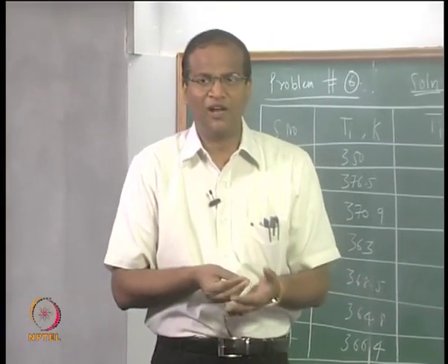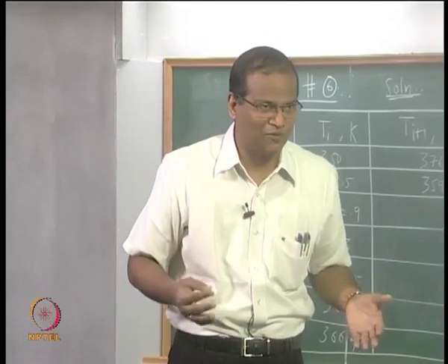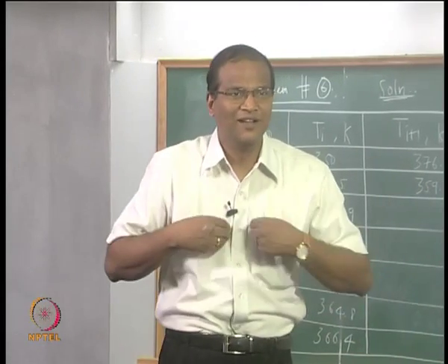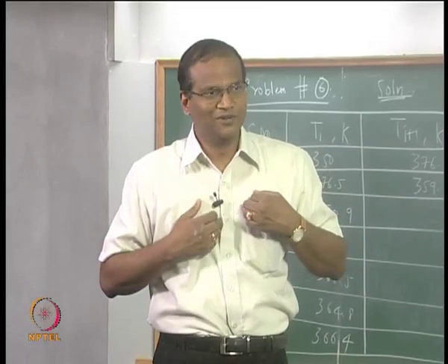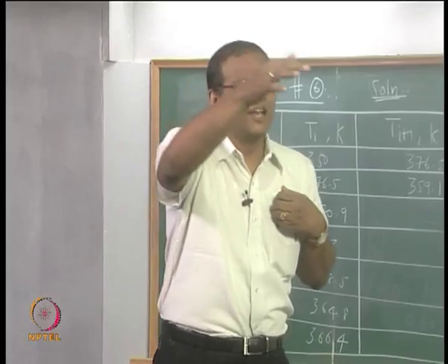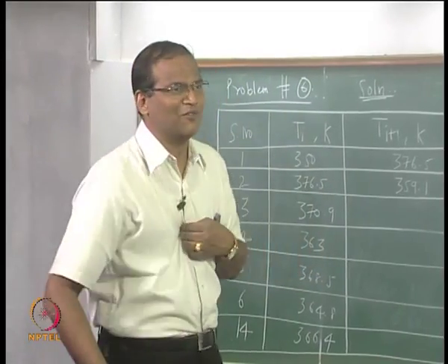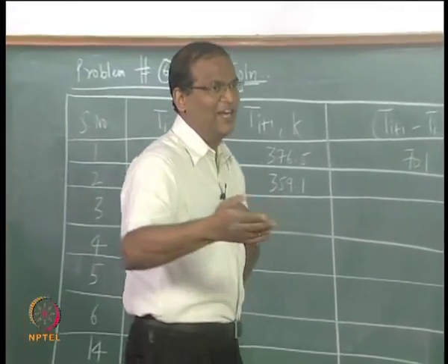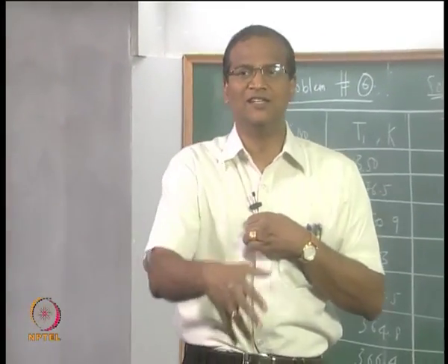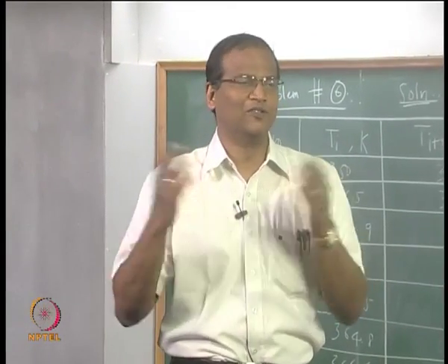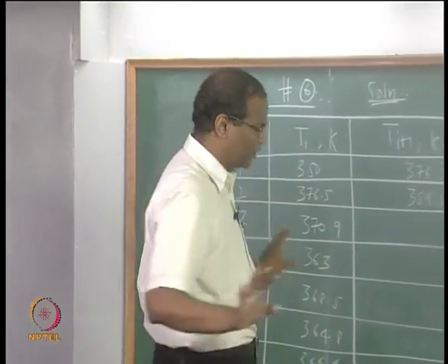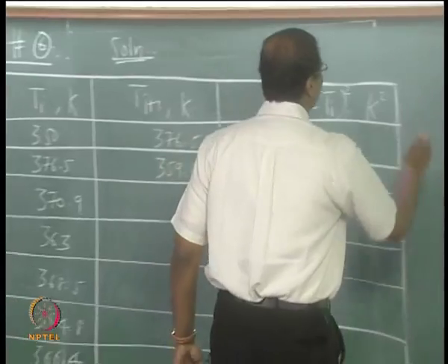In the exam, if you are given a highly nonlinear problem, you start with an information flow diagram and you do not get the answer, you are unlucky. Otherwise you have to take the derivative and all that, and the time taken for that is too much. You might as well start with this information flow diagram, proceed to the point at which the solution diverges, turn around and say that this information flow diagram does not work, so I will have to go back to the other information flow diagram. Is that okay?